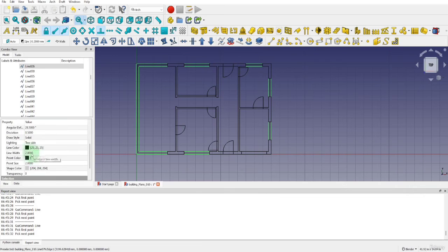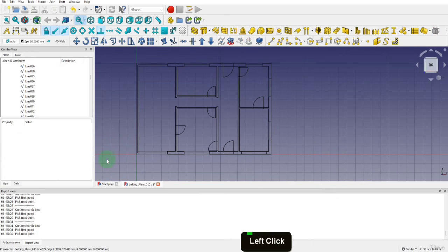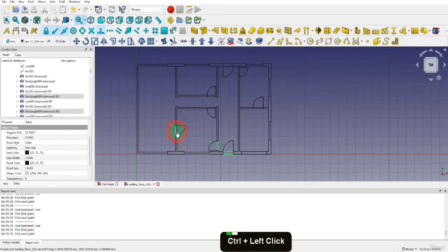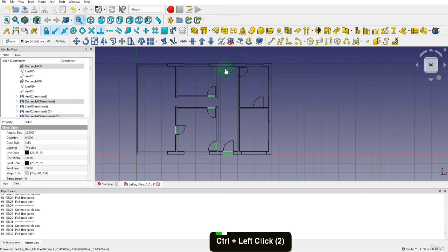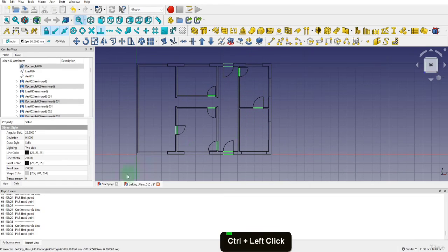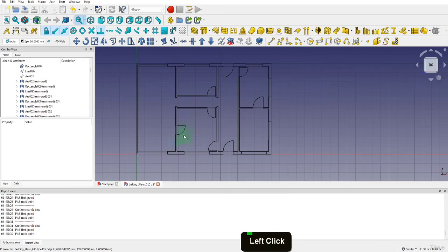Here we are looking for the line width property. Change this to 1 and reduce the thickness of the line. Click away to update the selection. We can do the same thing with the inside and outside door lines. Select each of these. Careful when selecting as a double click can sometimes deselect everything. With these selected, we can input 1 in the line width field. Click away and update those changes.